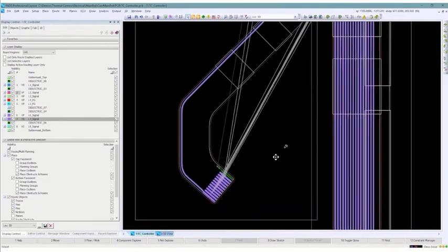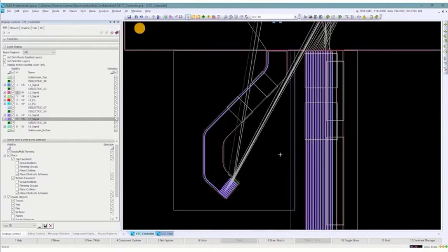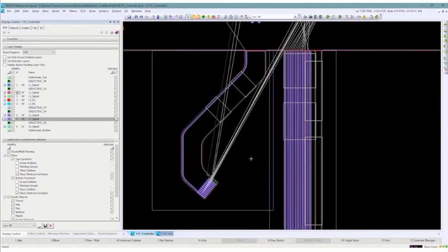And then lastly, again, we want to be able to customize our plane shapes based on area, because in our flexes, we generally don't want solid copper. You want, especially ones that are going to bend at a fairly tight radius, you want to use hatch copper, because solid copper produces more stress on the flex. Any traces that are on the other side of it will end up with more stress on them, and they could be more likely to break over time with vibration or dynamic movement.